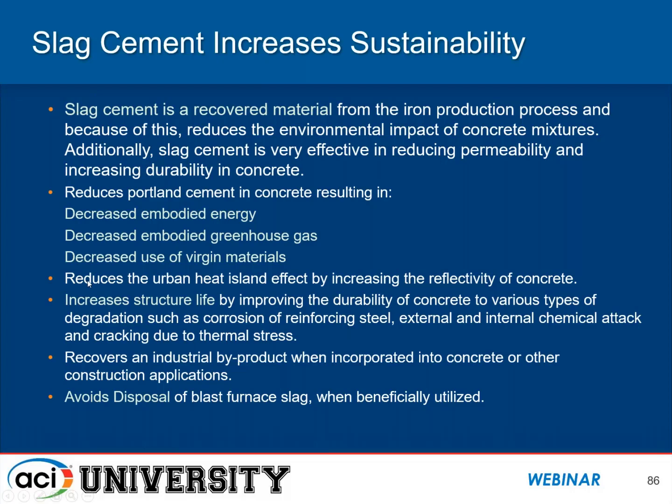Because of the lighter color, you reduce the urban heat island effect, because the higher reflectivity of the concrete reduces temperature rise in hot weather. And you're increasing the structural life by improving the durability against aggressive things like chlorides and sulfates, and cracking due to thermal stresses. And it avoids disposal of slag, which is beneficially utilized.